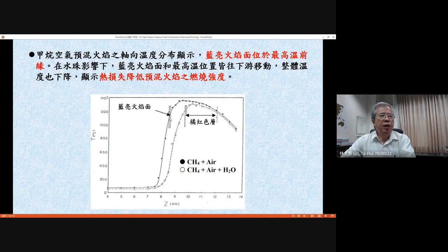At this position, the flow velocity is higher than at that position. You move further, and the velocity continuously decreases. This kind of velocity variation was justified from our cold flow experiments. Now, if the flame moves to the downstream side, that means the flame speed is balanced with a lower velocity, which means the flame speed is lower.